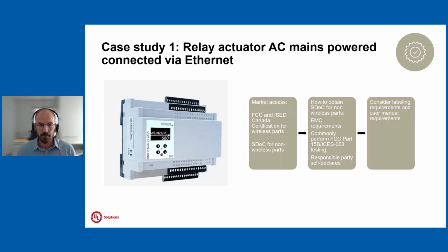Just a note here, I have not been mentioning anything related to UL standards or the electrical safety part, because it's not part of the scope of this webinar. I am aware that depending on the product category, there may be a UL standard covering the electrical safety requirements of a product that may require some immunity tests. That's a different story from FCC and Industry Canada requirements, and you will need to assess the product on both. So the UL standards may include EMC immunity tests related to the safety function, but the FCC and Industry Canada rule parts and standards concern emissions in the EMC.